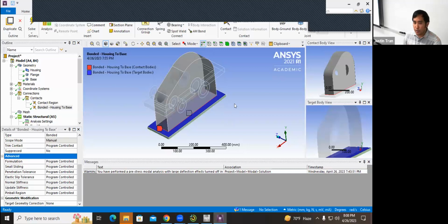For direct optimization, you can say I want all the frequencies to be less than this, or the range of frequencies to be this. If all you're interested in is the most optimal values of the housing thickness, the diameter, and the width, that's what direct optimization is for.